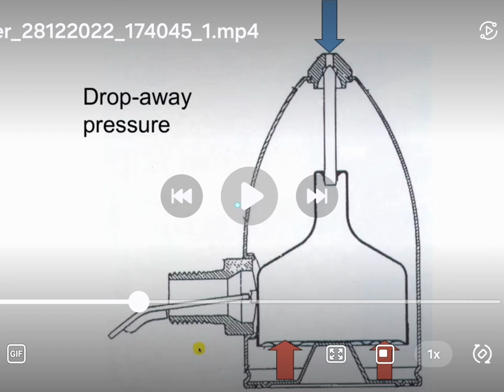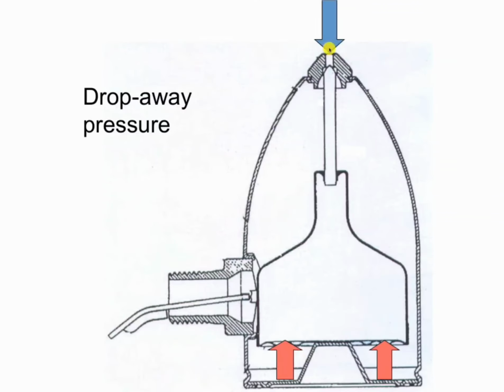All right, let's bring it back for a minute. When you got steam pressure on here, if it's on there all the time, this is going to keep the vent closed. Stays closed all the time. That was the challenge that we had with that New York City housing project that was taking Con Edison steam, which came in at a constant pressure and never dropped. The constant pressure just held the vents closed. And before the air is out, the radiator's full of air. The steam's trying to get in. The radiator won't get hot because the air can't get out. So we want to lower the pressure.